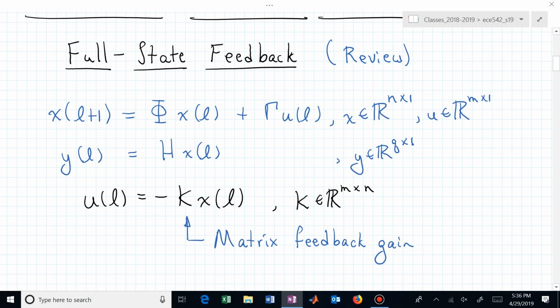And that just makes it a little bit easier when we start looking at transfer functions, but you could walk through the same derivation to obtain a slightly modified transfer function if you were interested in having a non-zero direct feed-through term in the output matrix equation for y.